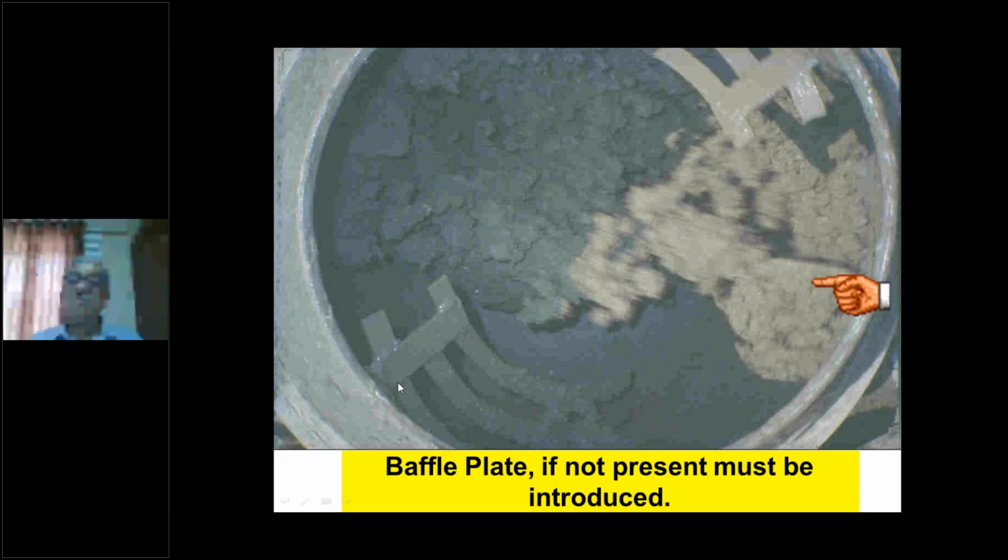Now if these baffle plates are missing, you'll have to introduce them on the site, and definitely you'll get much superior mixing. This photograph is of a Wingate mixer of the yesteryears when the British came to India and introduced concrete. The modern mixers, for God knows what reason, have forgotten the baffle plate.